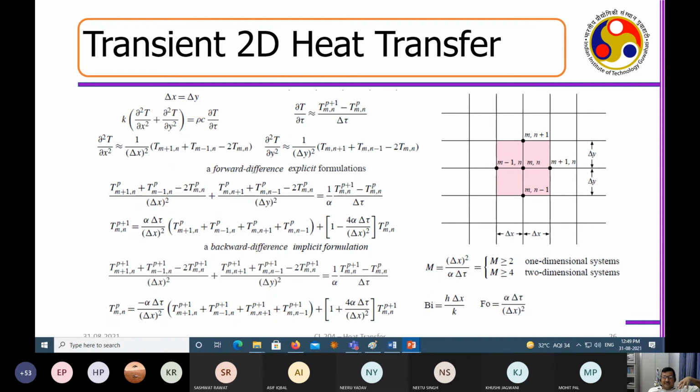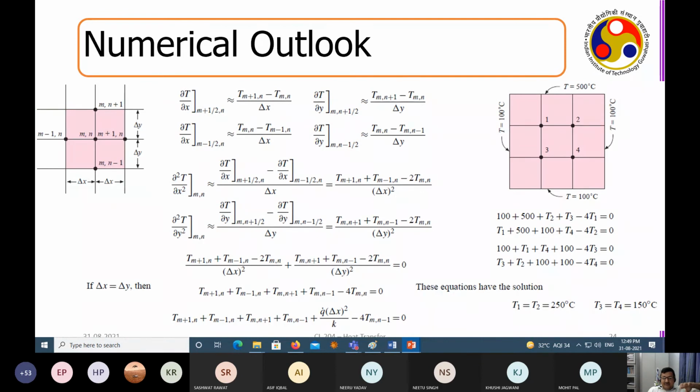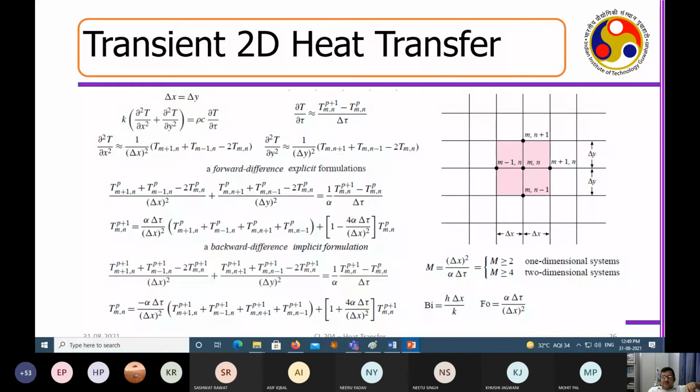And that computer program can be written. I have just given you the entire solution for this 2D conduction, 2D heat transfer. Now, in this situation, what we did was we just took del square T by del x square plus del square T by del y square to be 0. Now you can see that we have integrated another complication, the time component also. So how do we go about it? Space, we discretize the same manner, the way we have discretized the space. And in time, you may see how exactly we go about this.